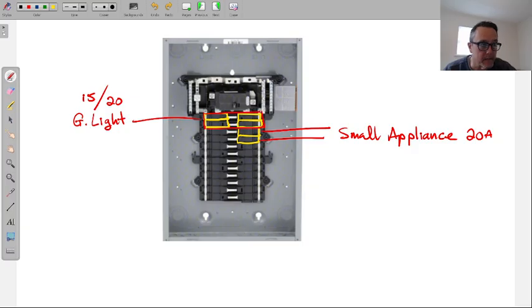Another thing that happens is, let's say you call me over to, hey, I want to add an outlet over here. Okay, I should just pick up an already existing circuit from any outlet that you have in the house and just pick it up from there. Unless it's going to be a small appliance, right? Unless it's going to be something, yes, exactly. You told me I'm buying a compressor. Okay, I'm going to give that compressor its own.